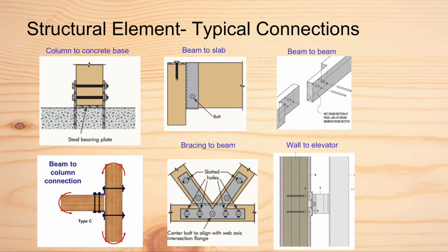Additionally, the shear strength of timber is only 1/10 of the bending strength, and bolt holes may also decrease the shear capacity. Thus, shear plates are adopted to provide additional shear strength. Dowel is applied to beam-beam connection since it can provide a flat and smooth surface.